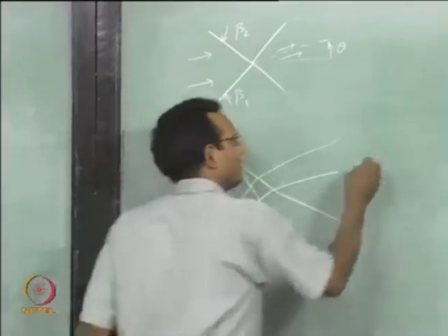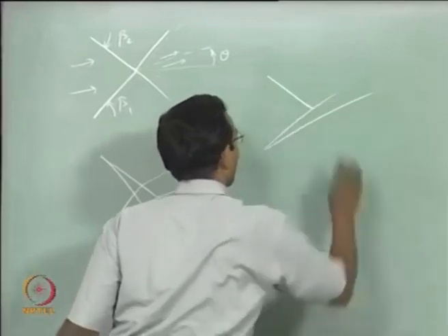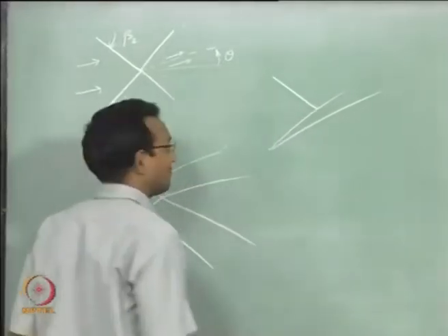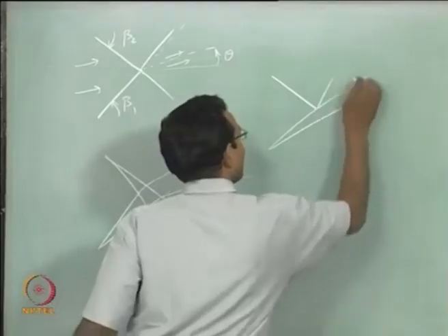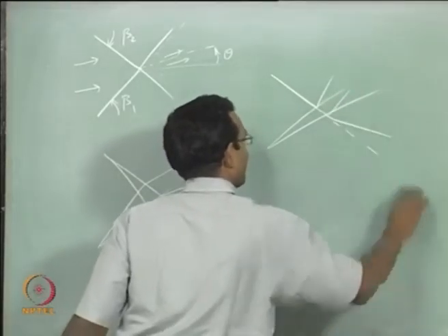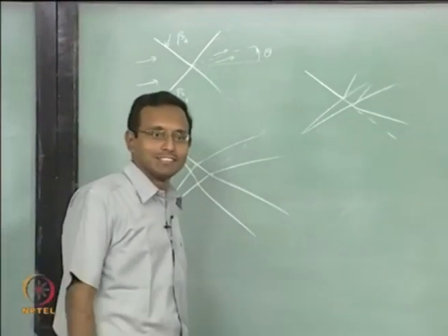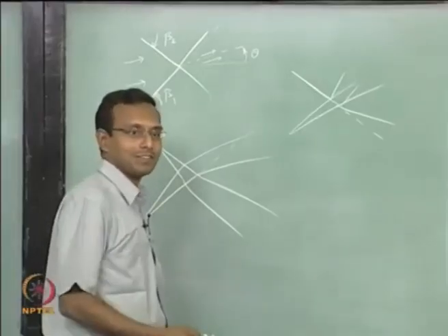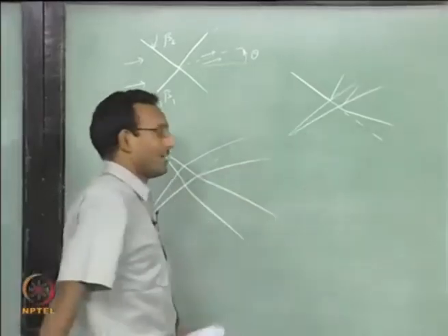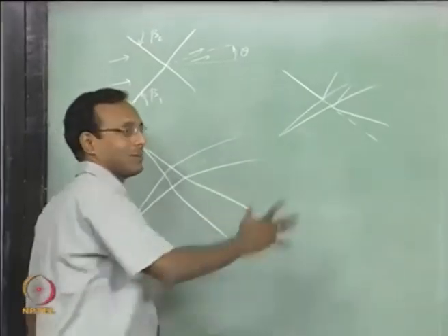These are easy stuff. Now I can think about expansion interacting with a shock, more complicated case. Okay. Now you will find that this will go up like this, while the shock will go down like this, downstream like this. That is what will happen. And all kinds of interactions like this can be handled after this. Okay. Once you know this, now I can go to any jet problem and start solving the jet problem. We will go there slowly.